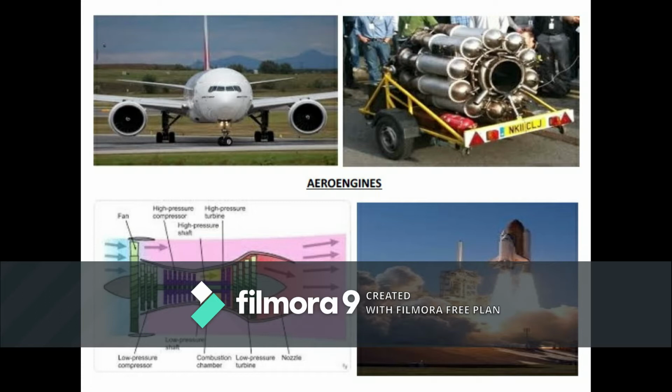Additionally, one propeller also will be fitted in front of the air intake. So whatever power is extracted from hot exhaust gases by the turbine will be transferred to the propeller. In this case, the propeller is the major component which produces thrust force, and through high velocity exhaust gases, only a small amount of thrust is generated. Okay, so this will be called a turboprop engine.